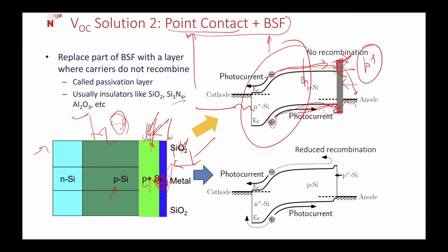With a crystalline solar cell, it is about 25-26% efficiency. To make it affordable, amorphous silicon solar cells can work as well, because on our roofs we do not have a limitation of space. To get the same energy, we just need a bit more area.